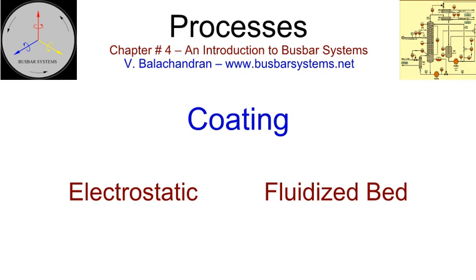Most of the designs meet the specified criteria with bare conductors mounted on insulators. Air is the only insulation between the conductors and between conductors and earth. Consequently, there is a requirement for minimum air clearance. Therefore, for a given rated voltage and BIL, the enclosure size cannot be reduced beyond a certain dimension. The geometry of the conductor for a given current alters this minimum requirement.